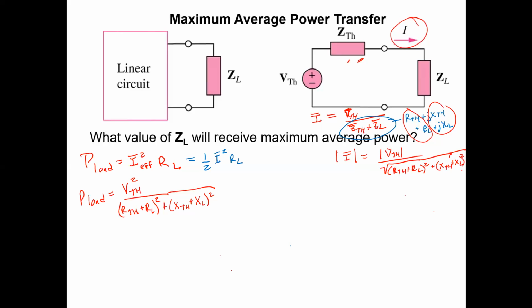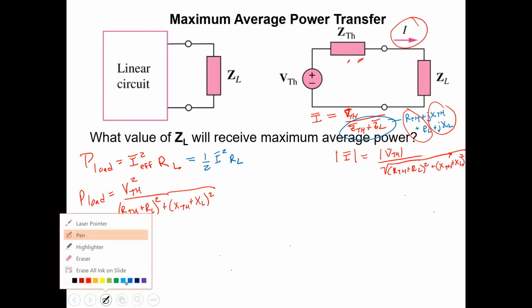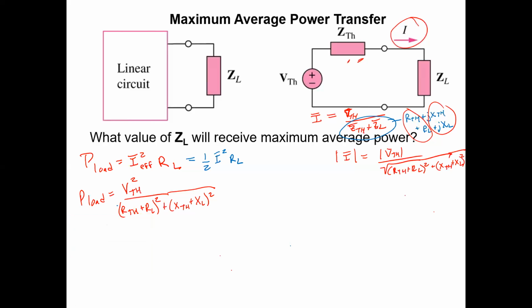Because when you square that, you get this thing, and this is going to be the magnitude of the power. And of course, if we're doing it with magnitudes, not RMS, we have to divide this by 2 to take care of that. So we'll leave the 2 in there just to assume that we're using magnitudes, not RMS values.